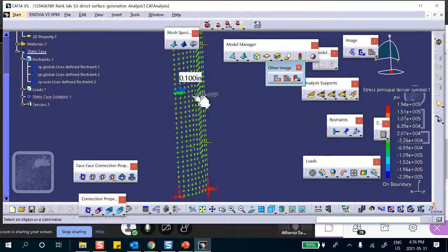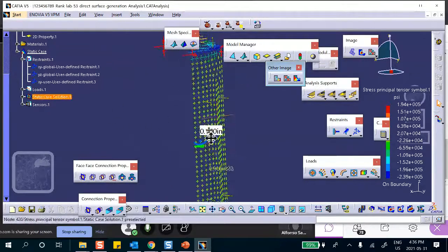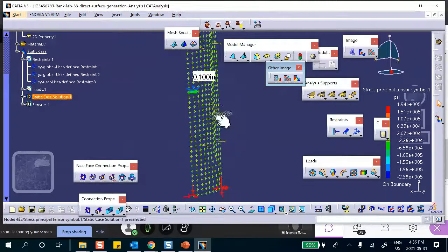Suppose there was an opening here, which was an attachment to some other gadget, a pipe or whatever. This PR over T and PR over 2T is totally useless. Those are useless because the PR over T assumes that you have a uniform wall, a uniform geometry. But if there was a hole here because you had to pump in air or whatever in there, then forget about PR over T.